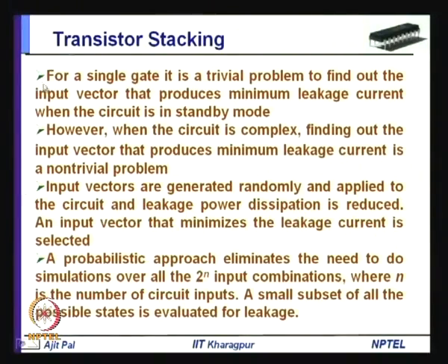Some heuristics are used to identify a subset which can be applied to the circuit, and from the input combinations generated by that heuristic algorithm, you find the one which gives minimum leakage power. However, you cannot claim that this is the minimum possible, only that it may be closer to minimum.